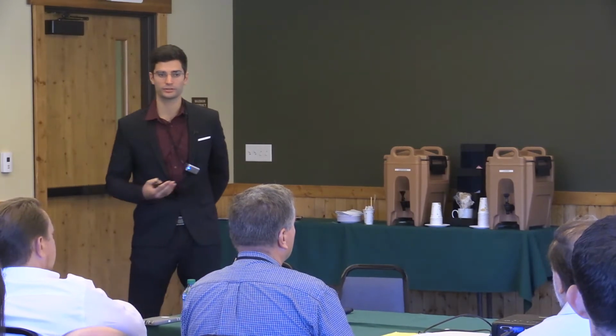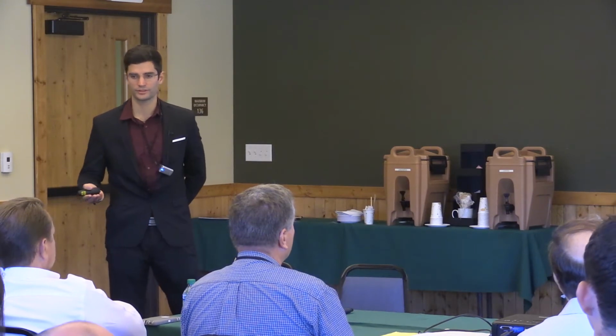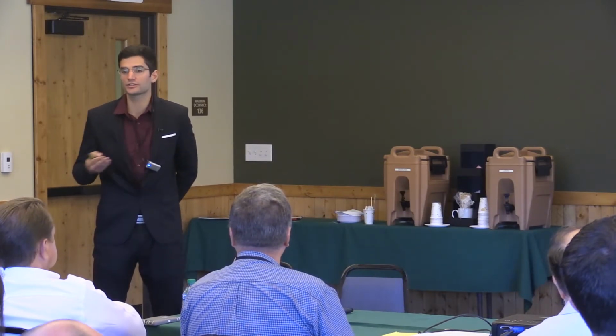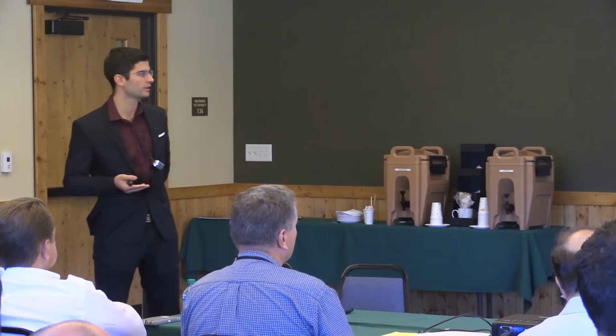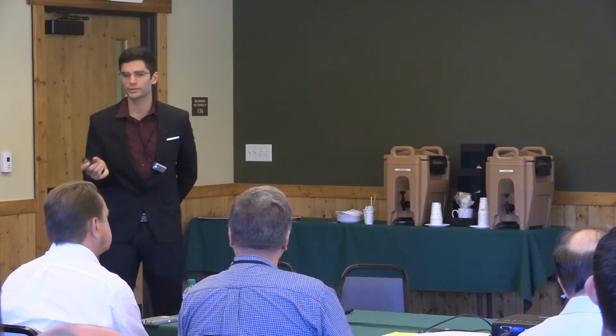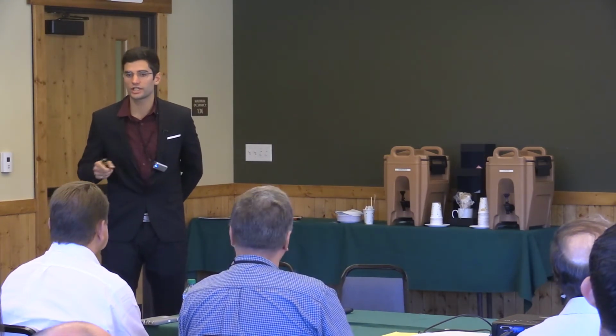But if we already have the voltage capacity in our amplifier, so the amplifier is able to provide 200 volts at the frequency we're driving the thruster at, then we don't need a transformer, because that would bring extra effects to the thruster, to the electromechanical system, because actually a transformer is not ideal. It has internal resistance. It can be magnetically saturated depending on the core that you use, and so it all has these real effects that could change the spectrum of the thruster.